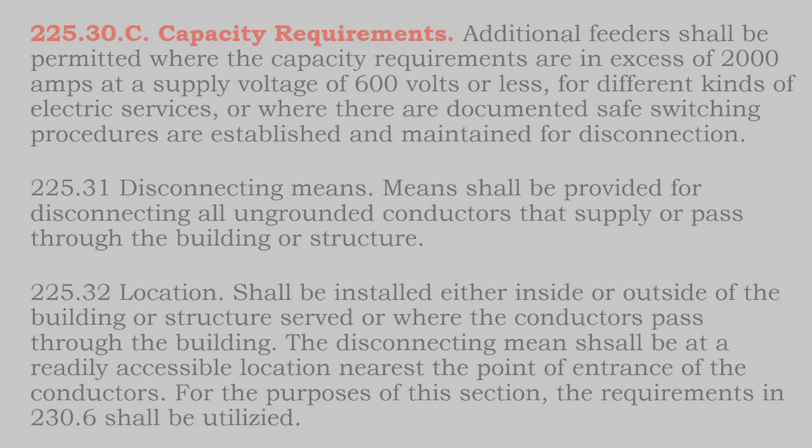If it's inside the building, A, it looks good. And to sell residential arrays, you've got to make it look good to be in the business over the long term, value is what we're talking about. When you're inside the building, it's not exposed to the weather. You get some really mean squirrels out there. So when you go into the roof, there's actually a box up on the rooftop that doesn't always disconnect, but can disconnect. It's part of your rapid shutdown system.